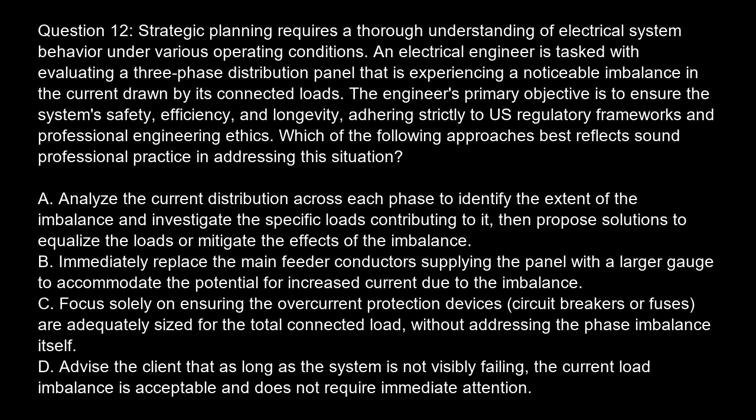Option A. Analyze the current distribution across each phase to identify the extent of the imbalance and investigate the specific loads contributing to it, then propose solutions to equalize the loads or mitigate the effects of the imbalance. Option B. Immediately replace the main feeder conductors supplying the panel with a larger gauge to accommodate the potential for increased current due to the imbalance.